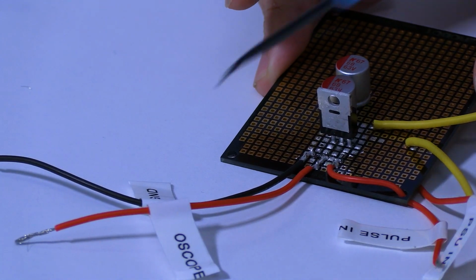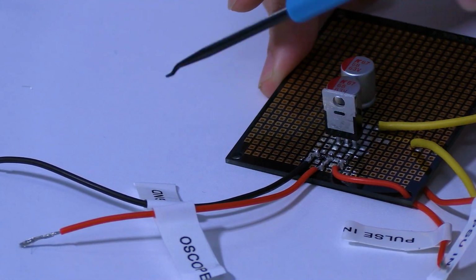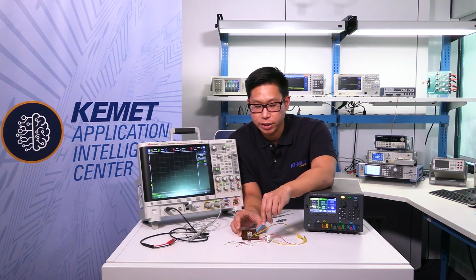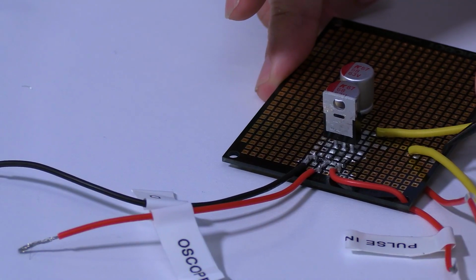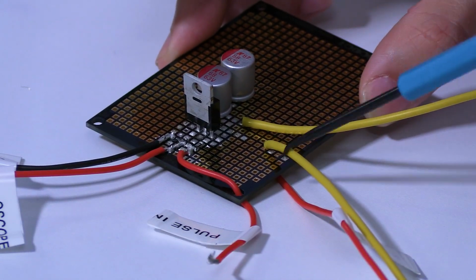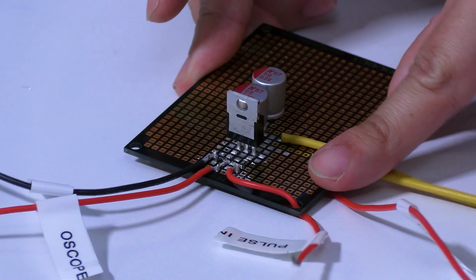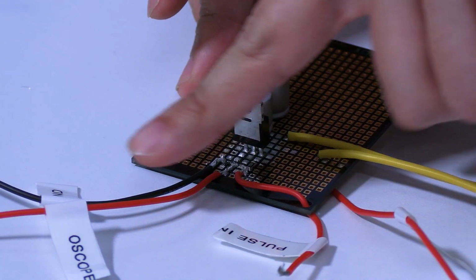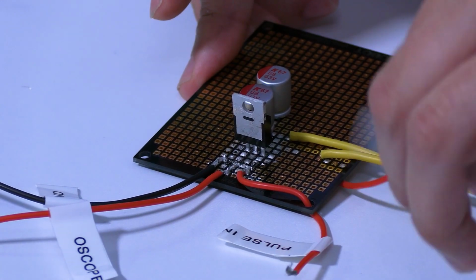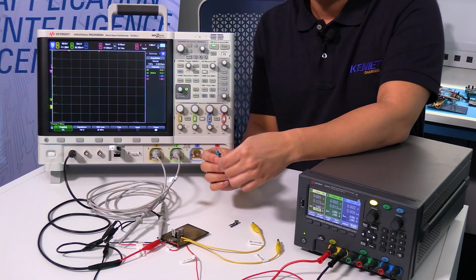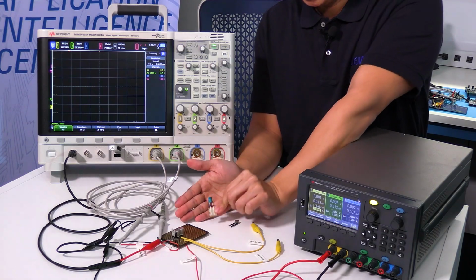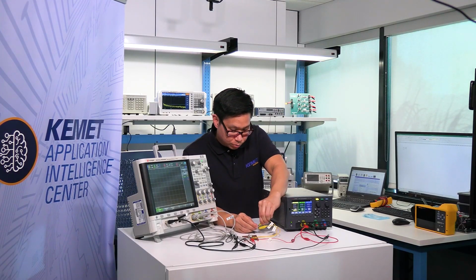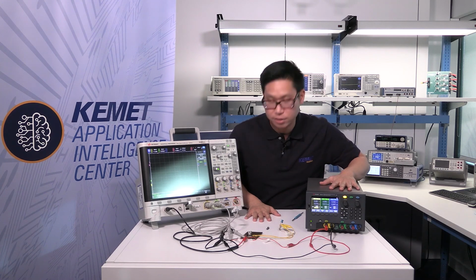And then these two inputs will be our oscilloscope input. And we're going to be monitoring the current sense resistor, which allows us to see current in a voltage form on the oscilloscope. And these two are for your inductor. So we'll be connecting our inductors here, our function generator here, our oscilloscope probes here, and our power supply on this wire. The first inductor we're going to test is actually the ferrite core inductor, which I have right here. Hook that up to the inductor input, and we should be all set up to go now.